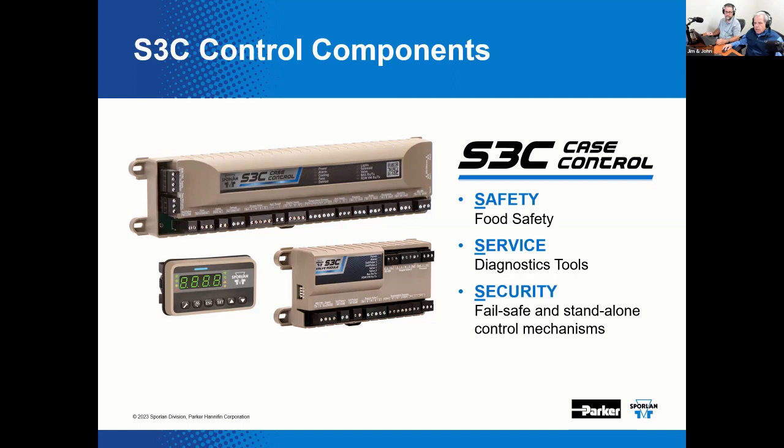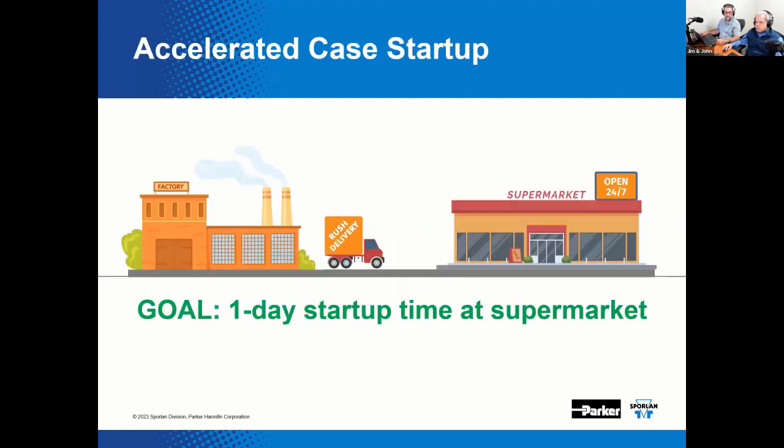In other less common instances, the building automation system, or BAS, could maybe be used to send all set points to those devices after they have been identified or addressed appropriately. So what are ways the S3C can communicate with the BAS, John? There's two ways, I think. It supports BACnet and Modbus protocols. I can barely spell those words. You did okay there. Yeah, thanks.